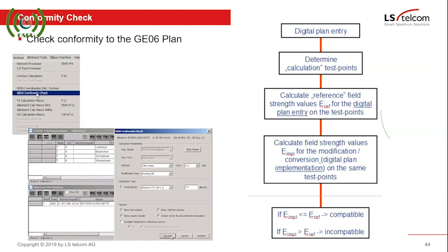So if one would have gone for a guard interval that will give you 159 kilometers between the two transmitters, then you are virtually free from interference, because there's very few times that you will have transmitters 159 kilometers away from one another, and then you will have interference.